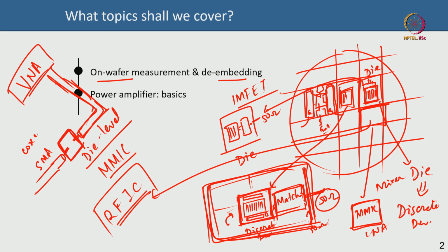The microstrip line will basically convert this propagating electromagnetic wave, essentially the RF signal in the SMA, to a planar form, which is a microstrip. It's a planar form, and then it will propagate in the semiconductor substrate. It will go through the device, mixer, amplifier, etc. So then the measurement is different. You are not talking about an on-wafer measurement, because it's a diced die.